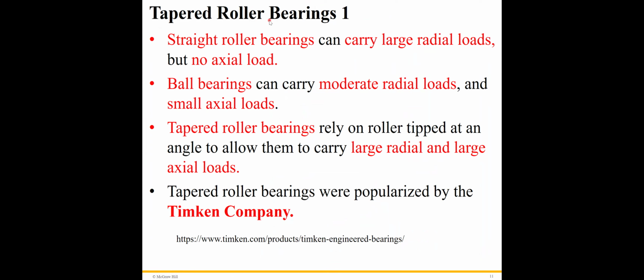If you still remember what we learned previously, the ball bearing can be subjected to majorly the radial load, with a small axial load. But the taper roller bearing can be subjected to high radial and axial loads.